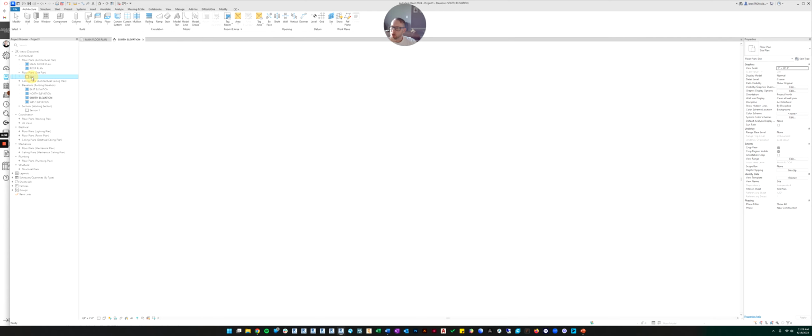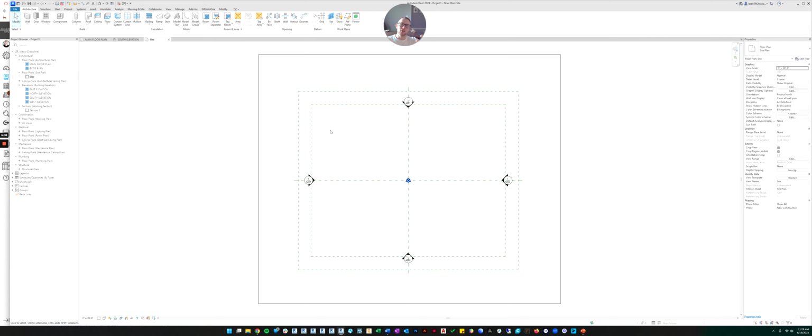They give us a site plan, which is nice. So that's a view that's up so high that it can see the whole project. Let's keep that. We'll probably want our L1, so the level 1 ceiling plan. Let's rename that. Let's call that main floor ceiling plan. We'll probably use that. We won't need something looking up from level 2, which we've renamed to roof level.